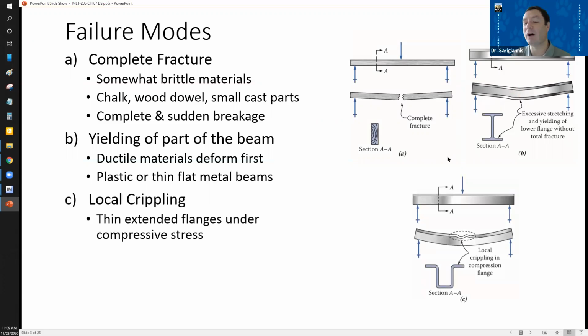So this is another reason why in skyscrapers and things, any steel structure, you have a fire, right? And if there's enough of a load and you heat up the metal hot enough and soften it, you're going to take the metal beyond its yield point. Remember, those yield points are for materials at a specific temperature, and that yield point changes with temperature. So then you'll get beams starting to sag and such in the heat.